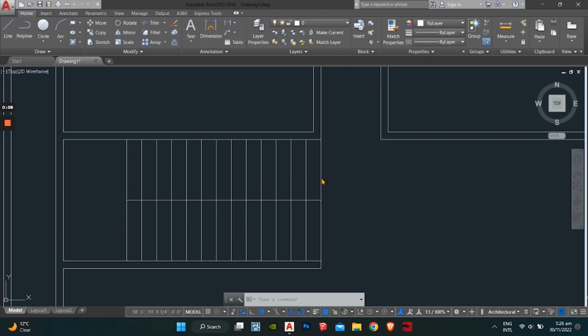So, 2 stairs represent 1 feet. So 1 feet, 2 feet, 3 feet, 4 feet, 5, 6. Okay, 6 feet here, 6 feet here. So the total height that we are achieving using these stairs is around 12.5 feet. So that's more than enough. Usually the houses are around 11 feet high, so that's fine.